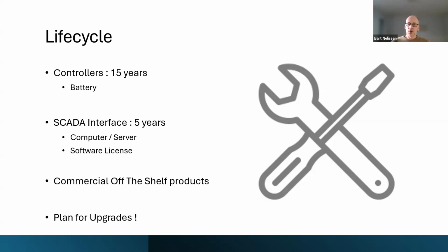But your SCADA host or your SCADA interface, which is running on a computer or a server of some kind, has a much shorter life cycle. And the recommendation is to replace that computer every 5 years. And it's probably no different than the computers that are used by all of us to do our daily jobs. So plan for a 5-year life cycle on the hardware, where the software may even be less than that.